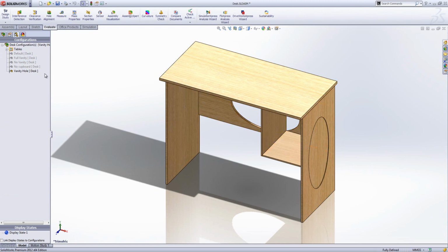So you can see it's really quick to create the tables, configure your features, your components, change the sizes of things, and allow SolidWorks to do the grunt work of creating and saving and controlling the table and creating the configurations for us. So like I said, I think it's just that little bit quicker and simpler to use than an Excel-based design table. Now, something you can't do, which you could do in an Excel-based design table, is add in equations to control things. That is one limitation of these. But as I said, nice and quick and simple.